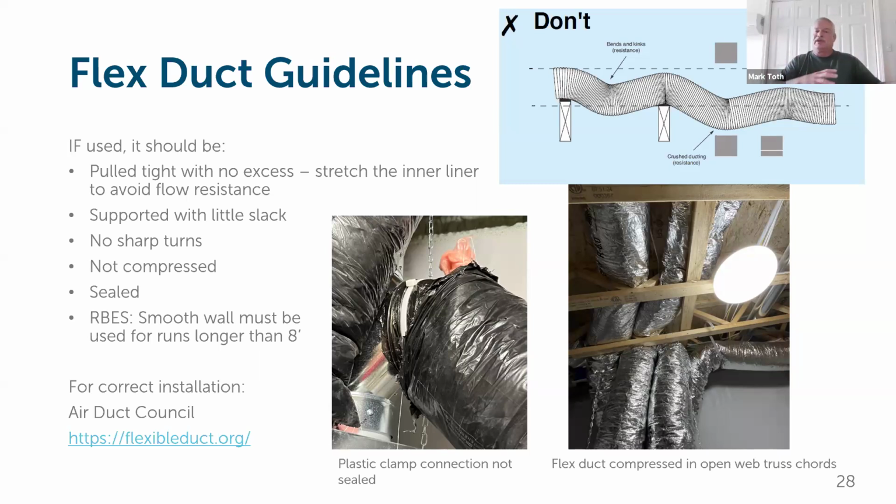It just creates strange sounds and moans. And every single time I've had that happen, if you disconnect the hard pipe from the unit and put in whatever you can fit, 2 or 3 or 4 feet of insulated flex at the unit instead of the hard pipe, that sound goes away 100% every time.